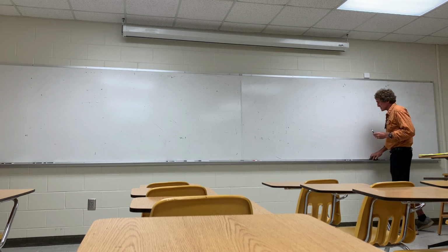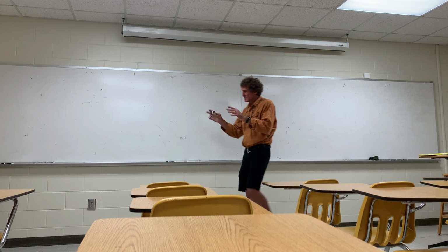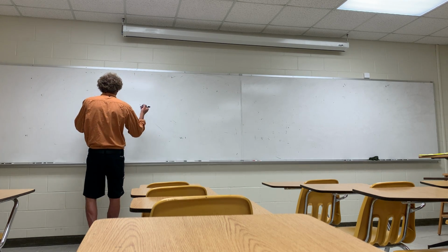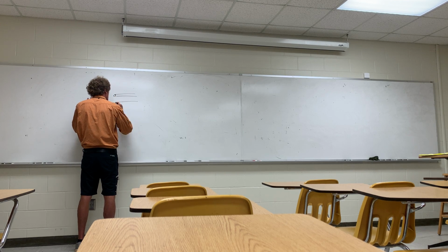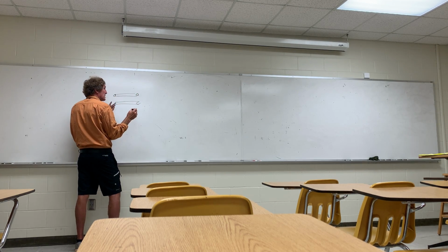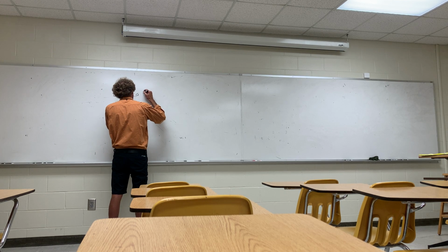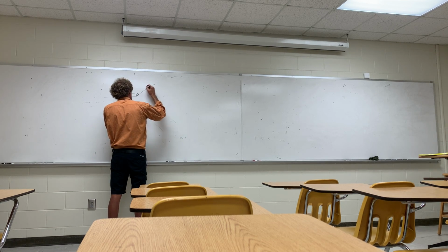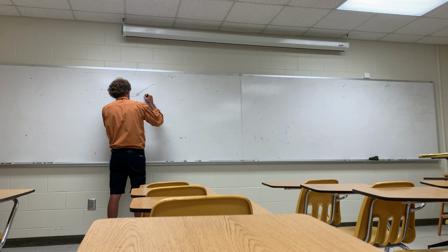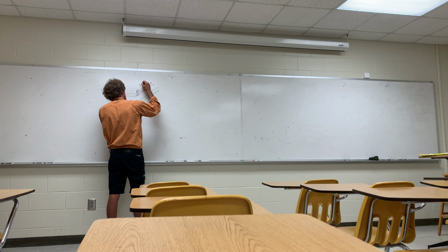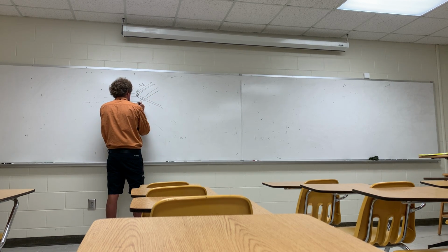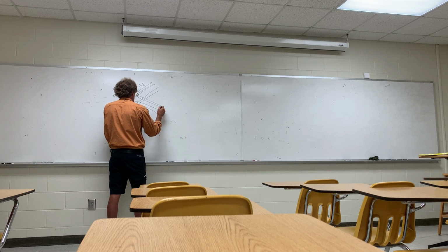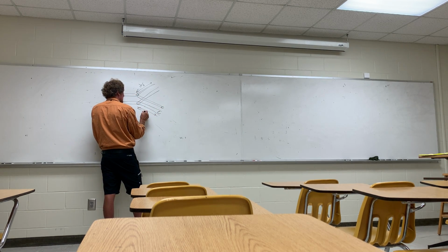So here's a Wilkinson divider. The book doesn't go into detail with it. It's a splitter, I'm sorry, I guess it's called a divider. They're going to have port 1 here. And then what they're going to do is have 2 different transmission lines that are both a quarter wavelength long. You're basically going to have a length of line here that's λ/4 long, and then another length of line that's λ/4 long.